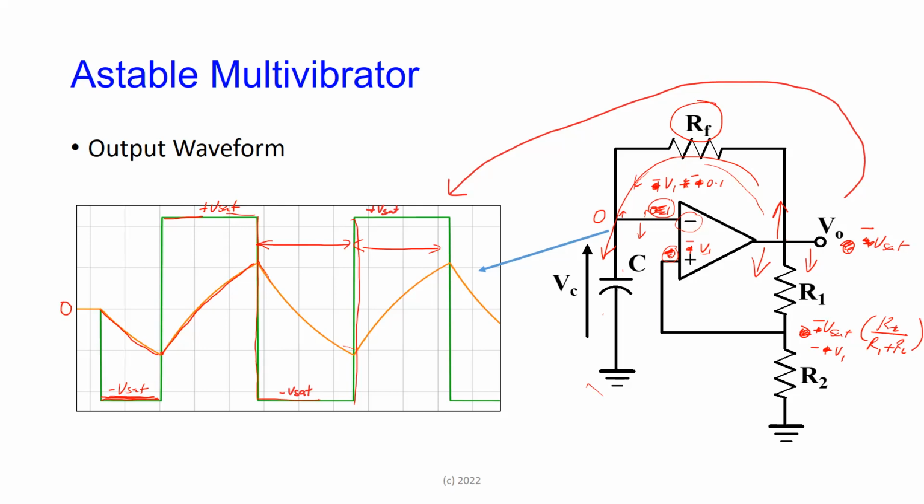So the bigger RF or C is, the bigger this charge and discharge cycle will be, so you can actually adjust the timing of the square wave. So that's clear now, we'll get to the little arithmetic in a while. But everybody understands the operation? Yes, sir.